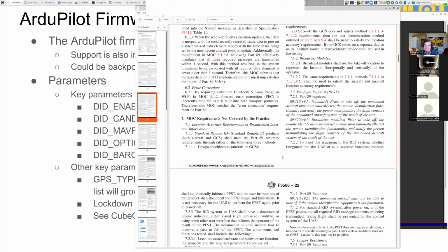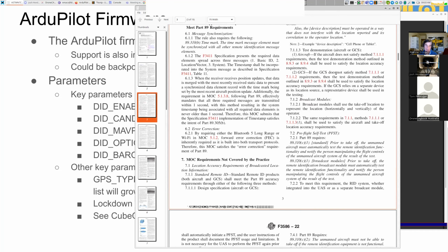And so at some point there's some level, but we could go to signing, we could go to public key crypto, we could have a private key baked into the ESP32 transmitter module, and then we could have a public key, and you have to encrypt and check the firmware. All of that stuff's doable. We're hoping we just don't need to, and our current reading of it is we expect that what I'm presenting today will be enough. It would not be massively surprising, though, to find that the FAA says, sorry, it's not enough, and we have to go back and start doing the whole public key thing, in which case working with Sid on the stuff he's done for India is likely the fastest way forward.